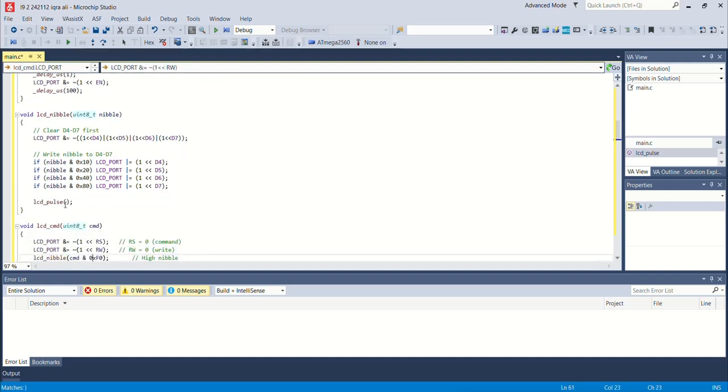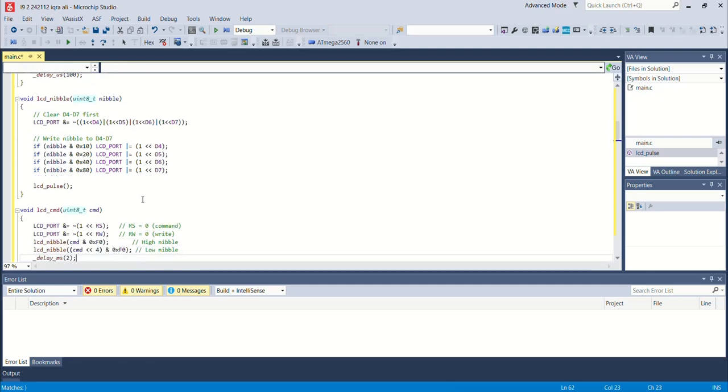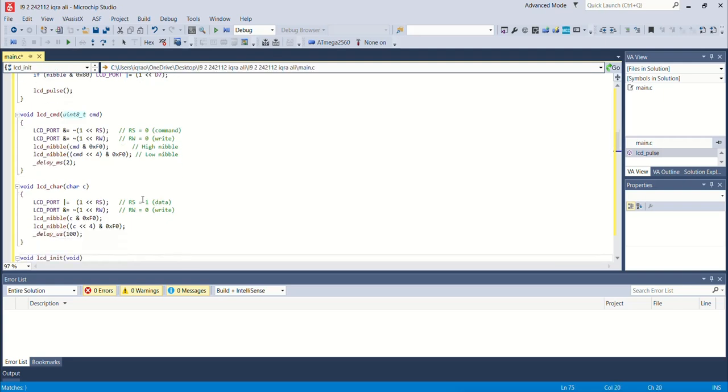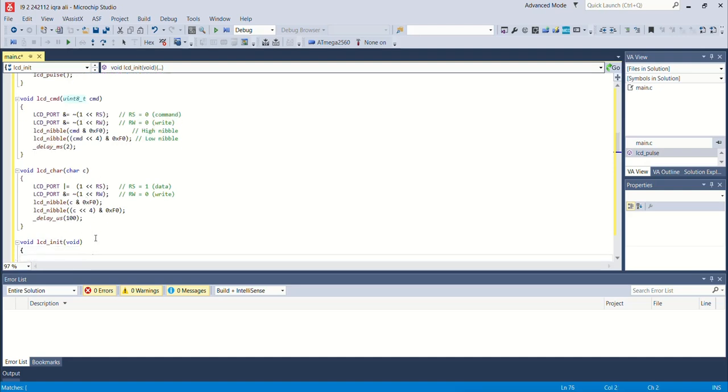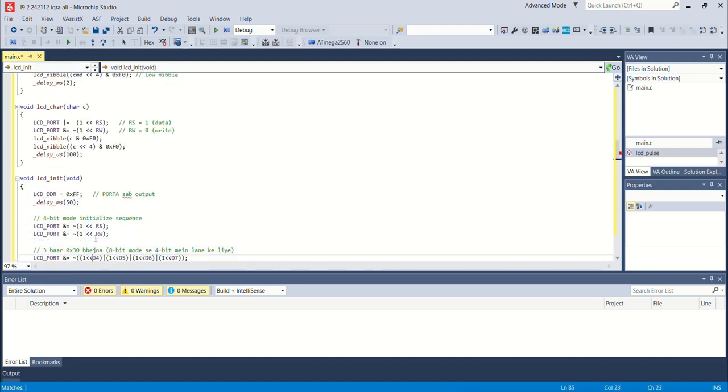First of all, we are clearing the ports so that we can store the data or the number on them based on the interrupt pressed. Then we are using the read and write command. This is the write command for the LCD, and this is for the character that we are going to display after 100 microsecond delay.